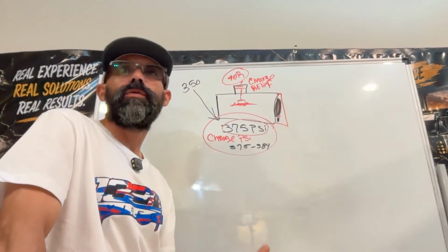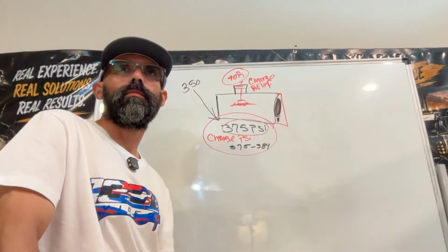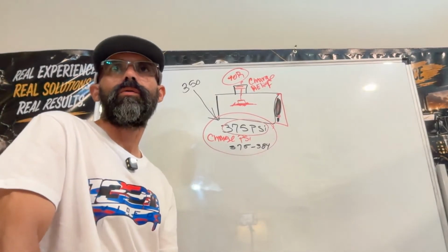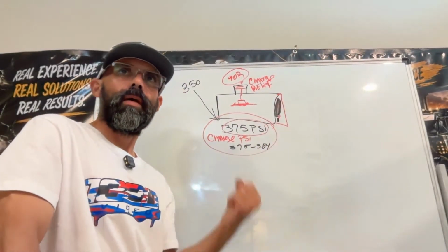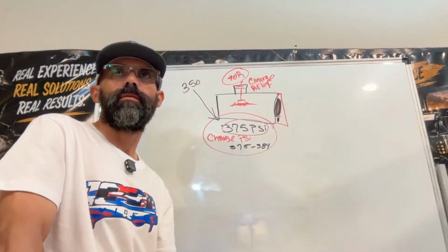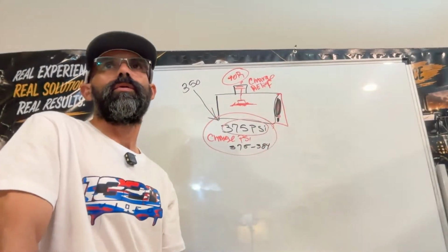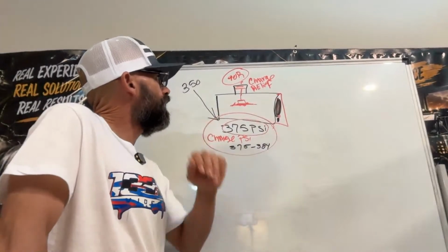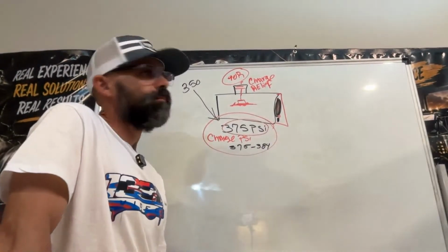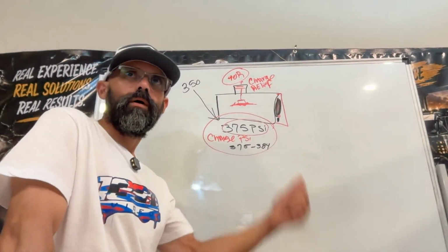So always use a gauge to determine why it's happening and how it's reacting. Basically, you're seeing behind the system by putting on a hydraulic gauge. You're seeing live data. So that's why you always need charge relief on this style pump.